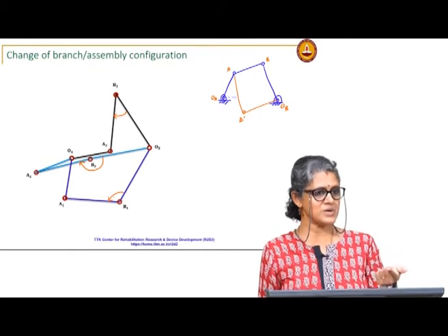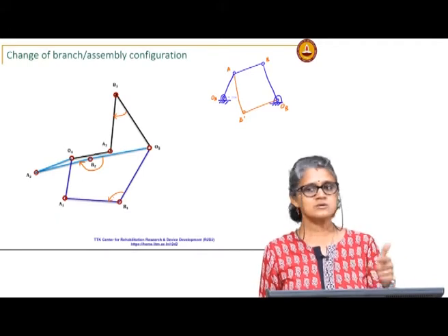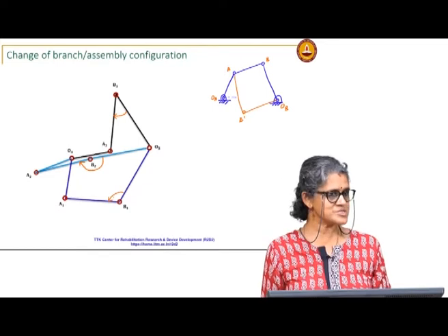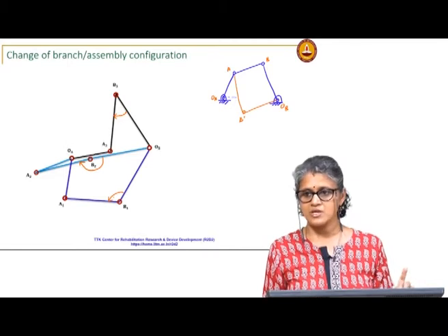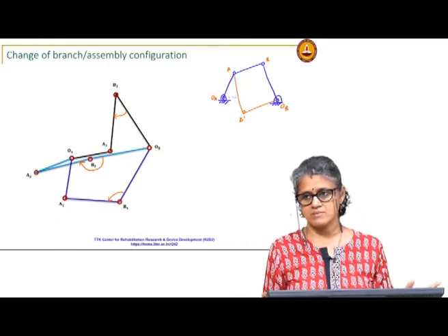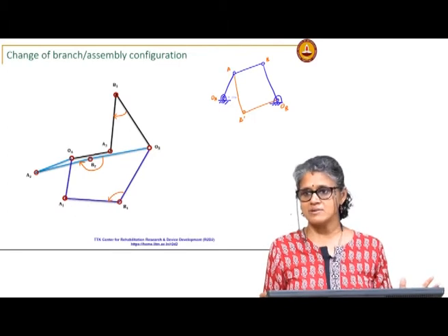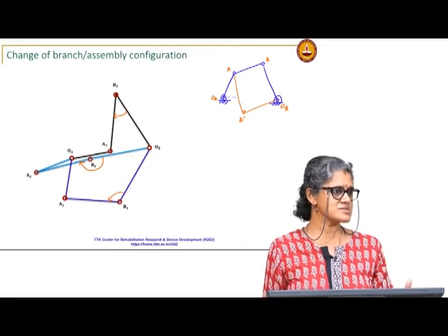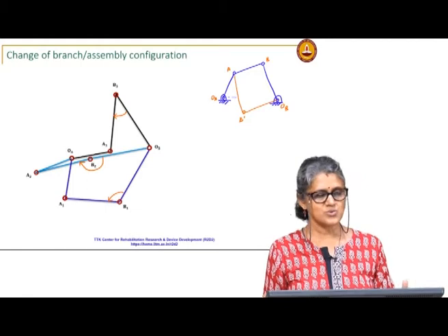So, that gives you an indication that it is not going to be able to reach all 3 specified positions in the same branch of the linkage. That means it is not a suitable solution for your application. So, with the graphical method you will just have to go back and try something else, maybe change one of the moving pivots.